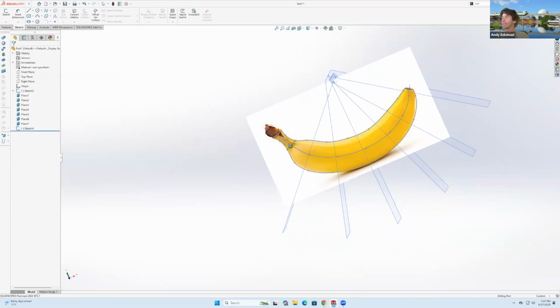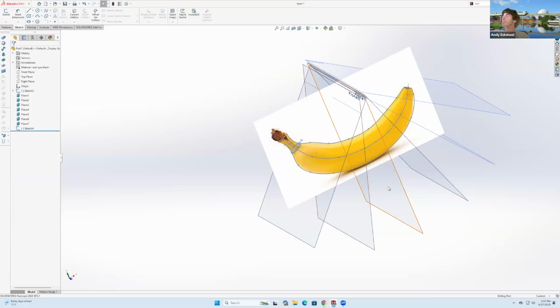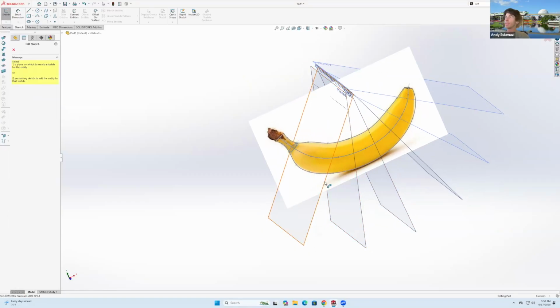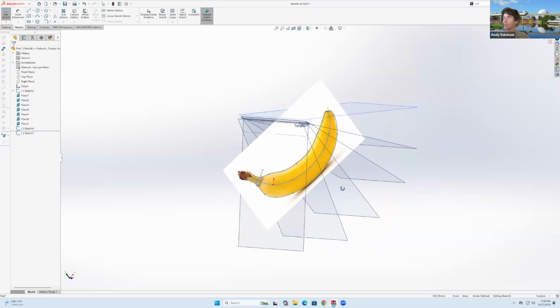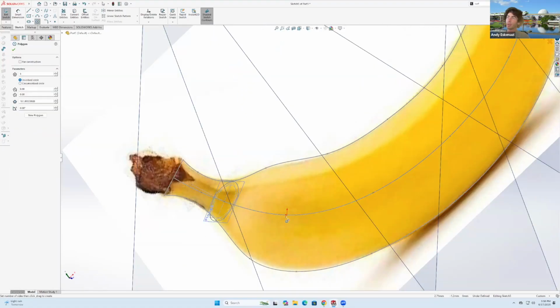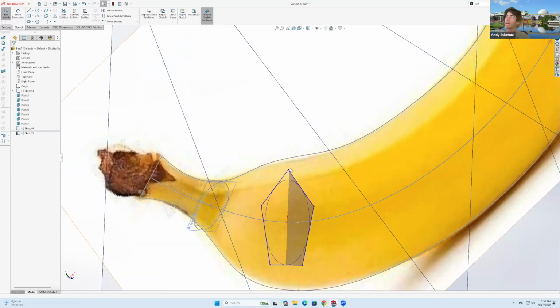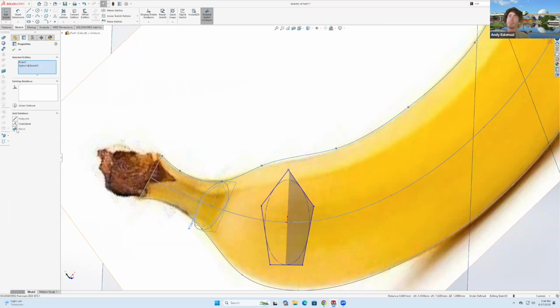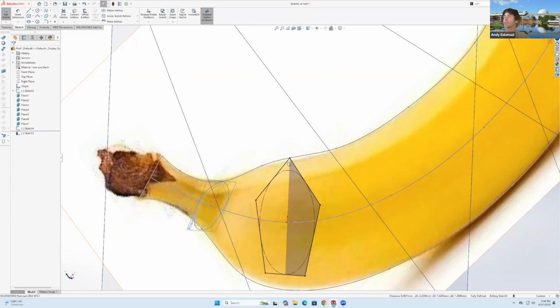So this process that I just did on that one, I'm gonna repeat it in each one of these planes. So now I go here to sketch. I go to plane number 1 now, this one right here, and then back to the polygon. I'll click in here, I go all the way upwards, and I'll click in this point, and I click in that line in there, and I can make that pierce perfectly.